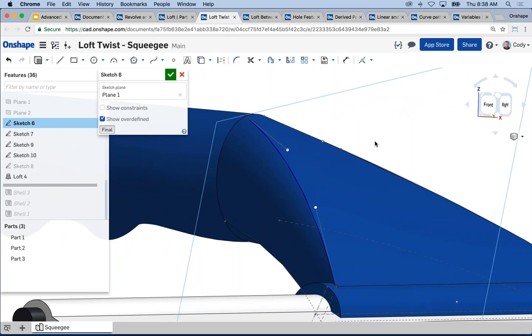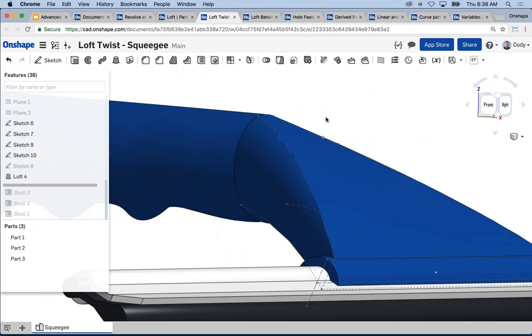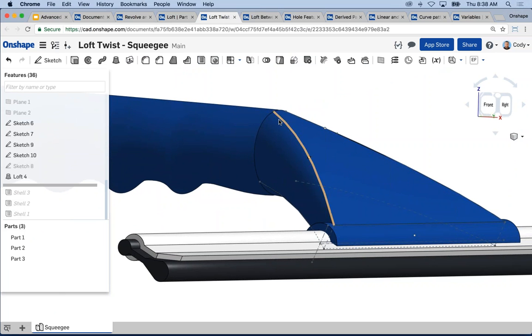So a tip is, again, the final button, and when you're using guides, this is a really useful tool, right? Again, guides, the key thing with them, they are going to take the most time. These are individually constructed splines. So, of course, this is what many would consider the last resort, but oftentimes if you want very specific control over the loft transition, it's the necessary thing to do, right?